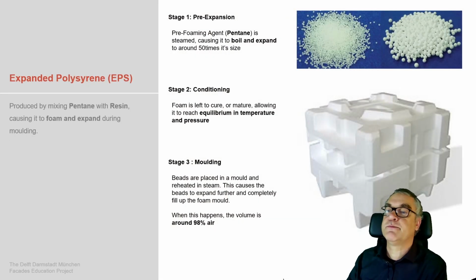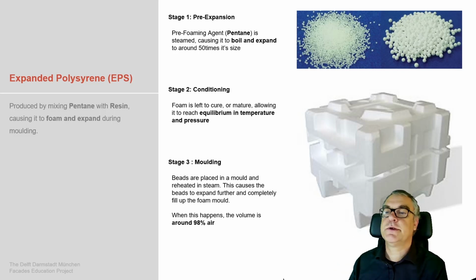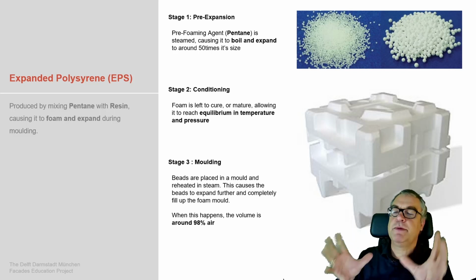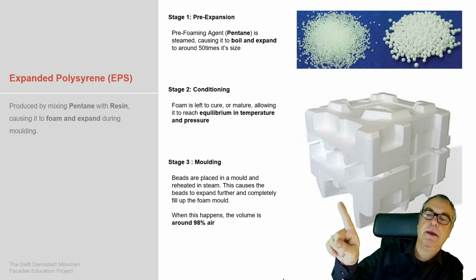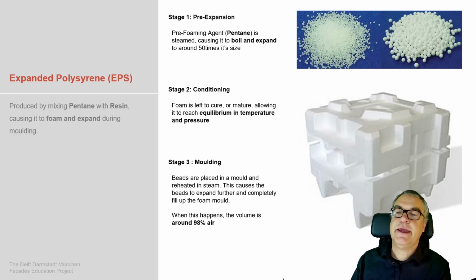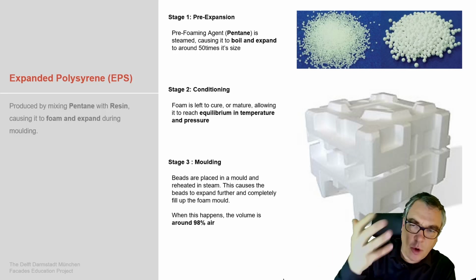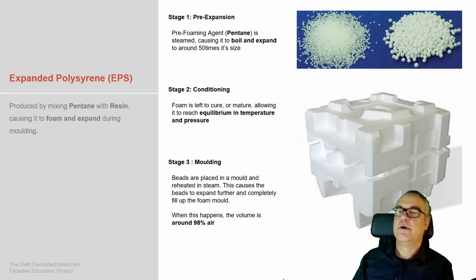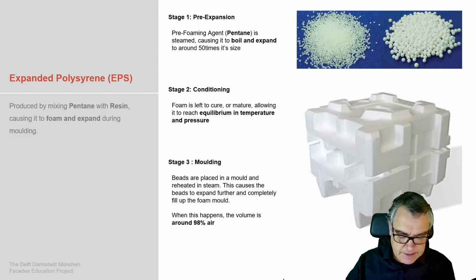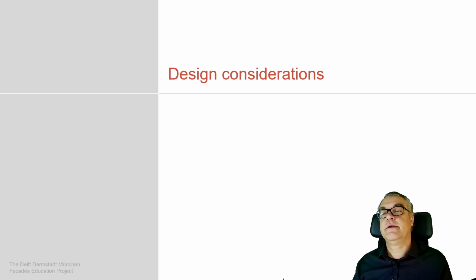Versus expanded polystyrene, EPS, which comes as an agent, is boiled to expand to a certain dimension, cooled down a bit, brought into the mold. That's what we see here. Quite a complex mold, which could be easily filled by reheating the agent and then the expanded polystyrene. The nice thing, which is always argued, yes, it's an oil-based material, but it's only 2% polystyrene, while the rest is air, which is then covered in the bubbles.